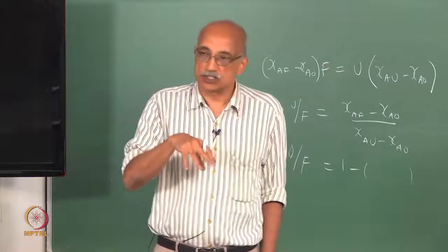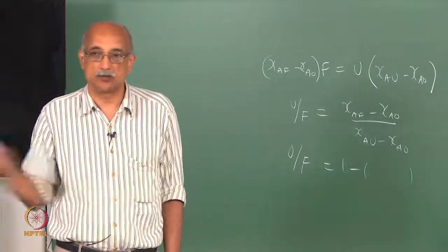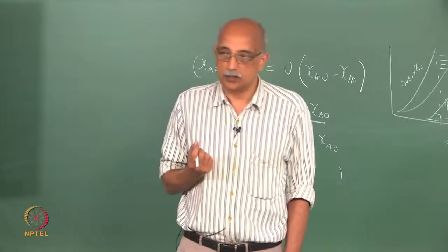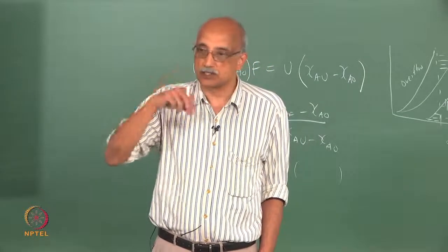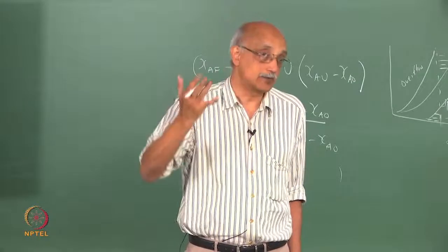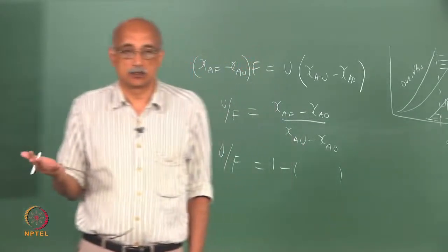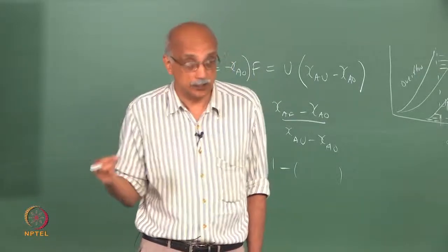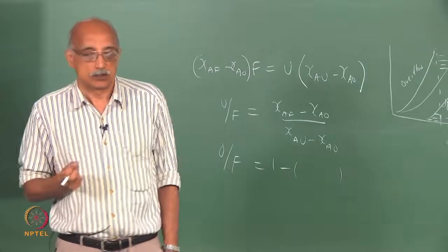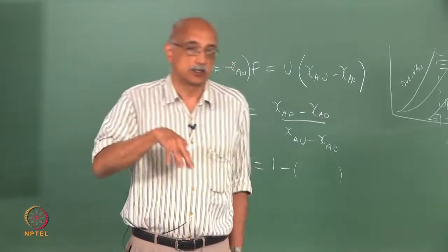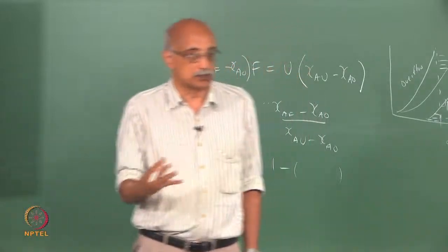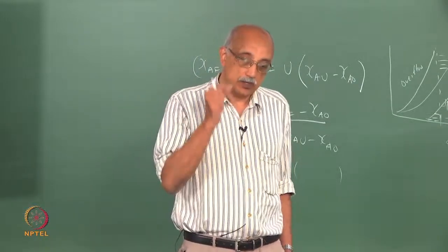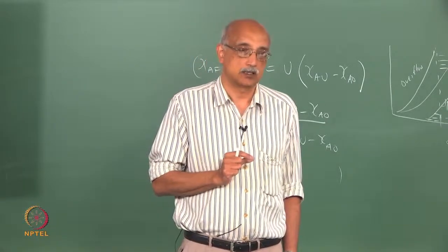So, for example, when you are trying to screen a particle mixture and you feed it through, the first time there is a chance that a particle that is supposed to penetrate may not, because of the various reasons I talked about. But if I have a way of recycling it, so instead of processing it just once, if I can process it say 5 times, the probability is eventually that particle will approach the screen at the right angle in the right condition, and it will pass through because theoretically it is supposed to. So, the number of impacts of a particle on a screen surface has almost a direct correlation on its screening effectiveness. And similarly, for each impact, what is the probability that it will get screened?